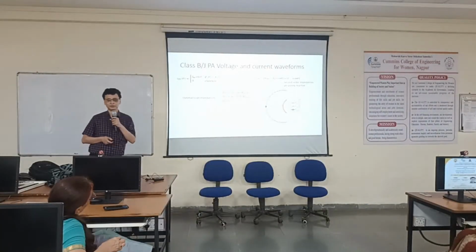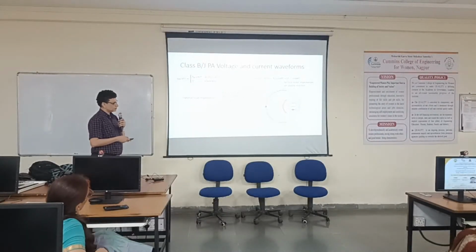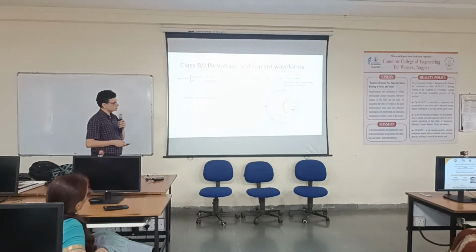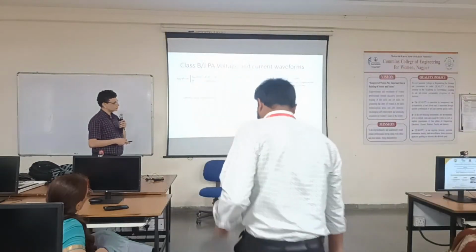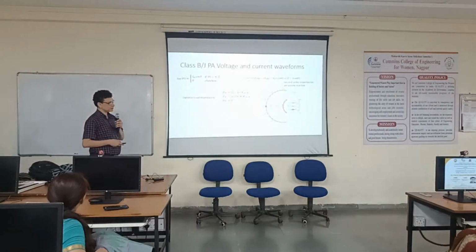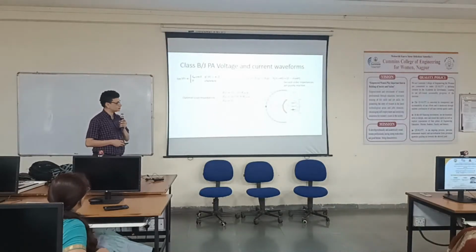Is everybody familiar with what a Smith chart is? Okay. So this is a Smith chart. It represents all passive impedances. This blue line represents all the second order load pull values, this orange line represents the fundamental frequency load values, and this black line represents the third harmonic.